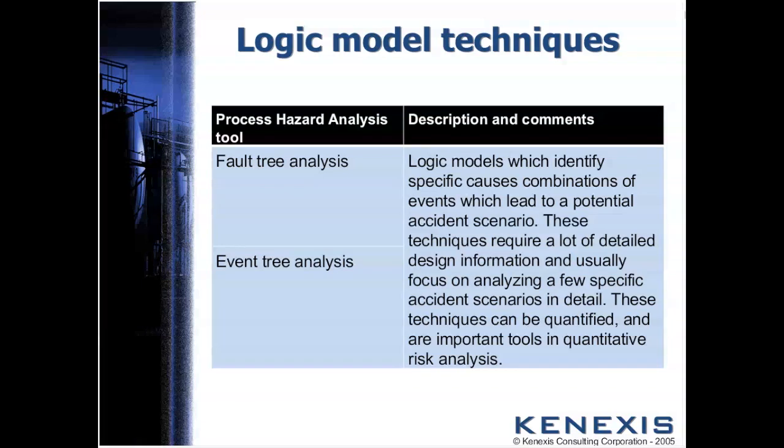I want to talk about fault trees a little bit. We use a lot of fault trees. They're usually used after a PHA has identified the very hazardous or complex issues. A very flexible and powerful method for modeling the failure characteristics of these complex systems.